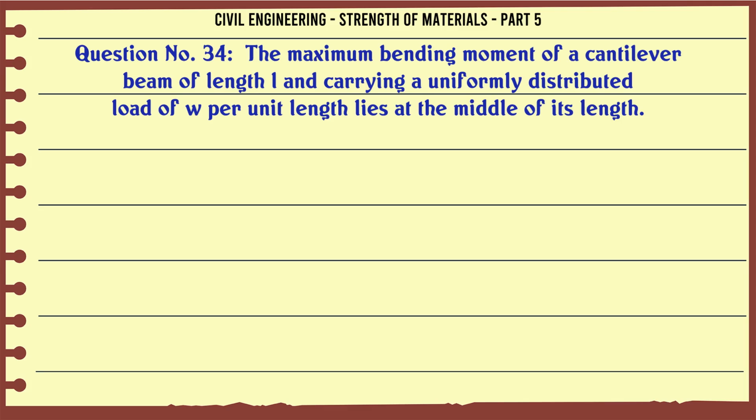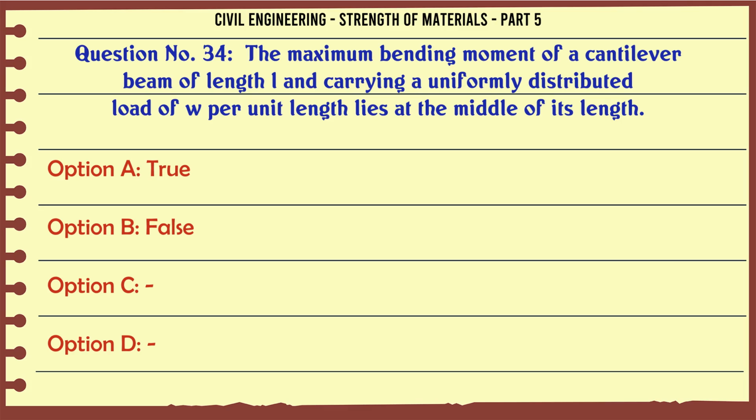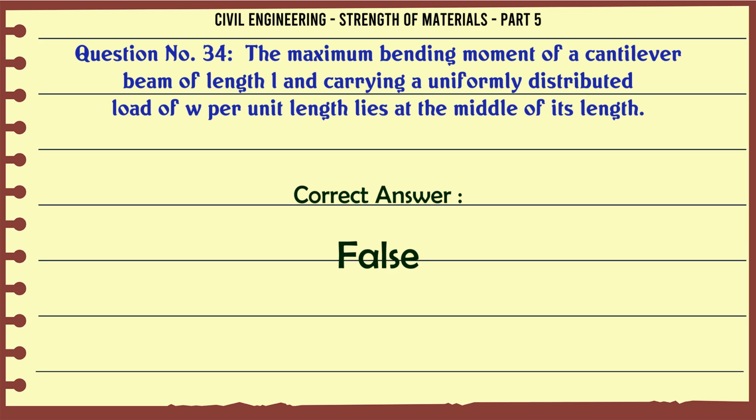The maximum bending moment of a cantilever beam of length L and carrying a uniformly distributed load of W per unit length lies at the middle of its length. A. True, B. False, C. D. The correct answer is false.